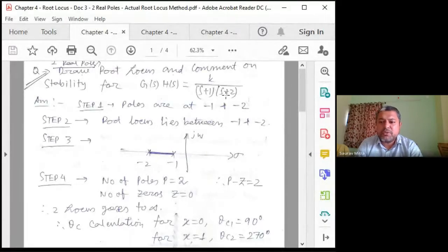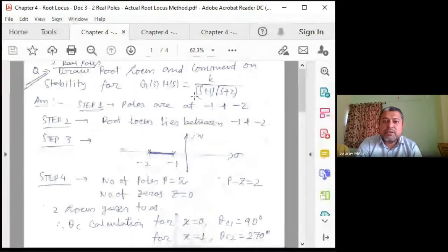I will show you all the root locus, and the biggest thing is we will do it on Saturday in one click. So you just define this G S H S and just write the command rlocus, and it will draw the root locus for you. जो root locus draw करने में तुमको आधा घंटा लगेगा, MATLAB will draw it in 1 second. Okay, so you will be given k into (s plus 1) into (s plus 3) divided by (s plus 2) into (s plus 4).